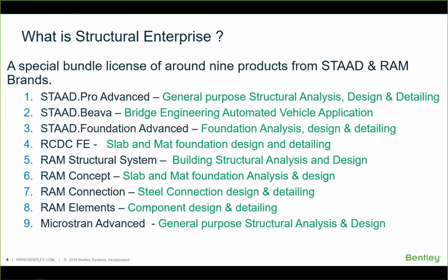in this presentation because now STAAD.Pro is not just an analysis and design program, but also a detailing program for both steel and concrete. And the second product is STAAD.Viva, which is a bridge engineering automated vehicle application. The third program is STAAD Foundation Advanced for foundation analysis, design, and detailing. And the fourth one is RCDC FE. This reads the file from STAAD.Pro, which is modeled as finite elements in STAAD.Pro. For example, a mat foundation model, which is analyzed in STAAD.Pro, can be read in RCDC FE, and we can then proceed with design and detailing.